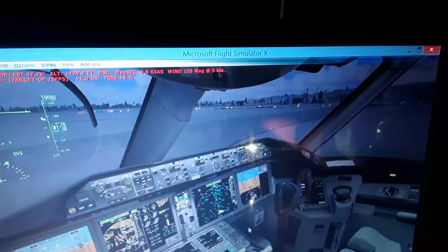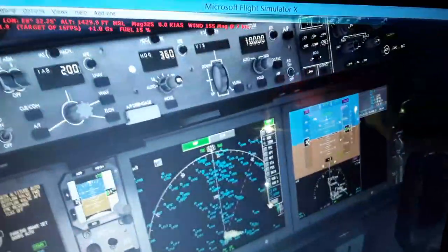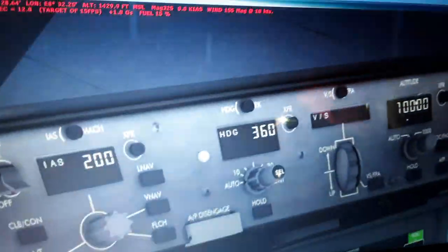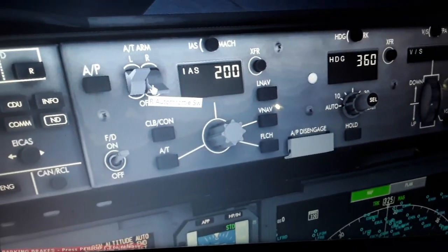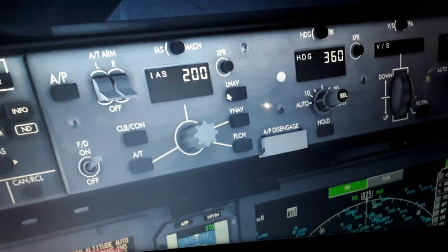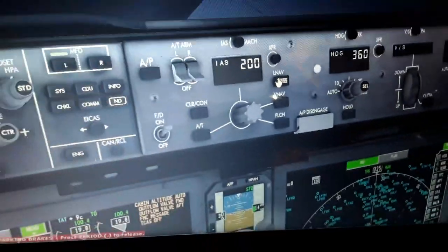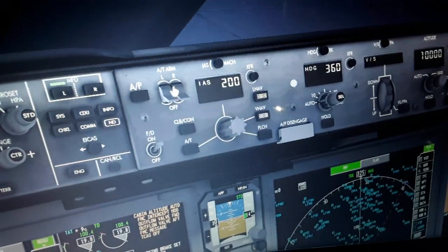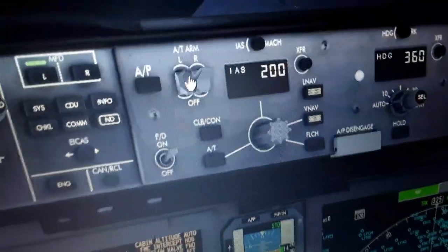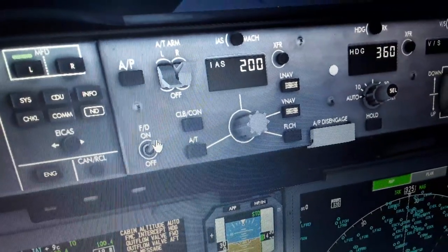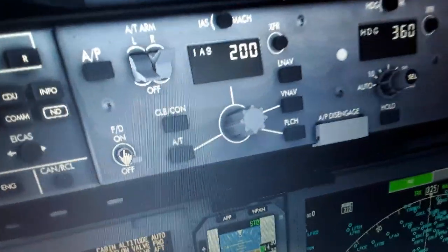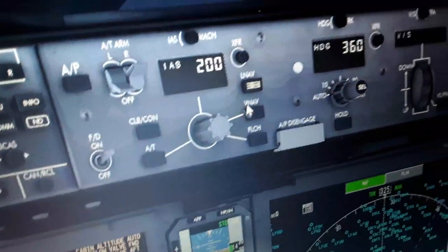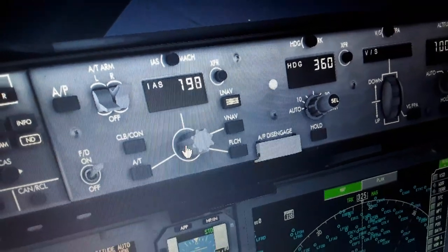We have now the autopilot flight director system panel. Just one second over here, I'm going to make the settings. So you can see the autopilot engage, disengage, auto throttle, left and right, flight director, the LNAV and the VNAV here. You will display something. So we have auto throttle like this, on and off, flight director off. If we turn off flight director, we cannot rearm the modes from the autopilot. We need flight director on all the time. So this might arm one or two modes.